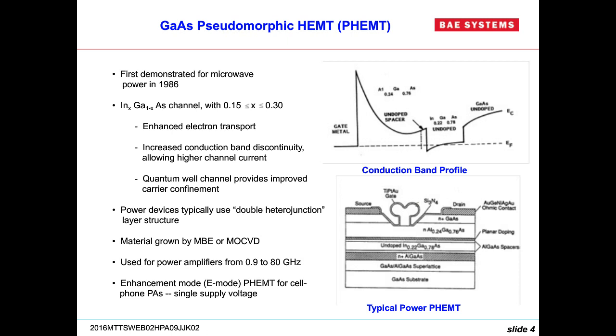There's another variation. Typically, these are depletion mode devices, but there's an enhancement mode device that was developed for single supply voltage operation for wireless type applications, and it is the principal competitor for the HBT in cell phone type applications.